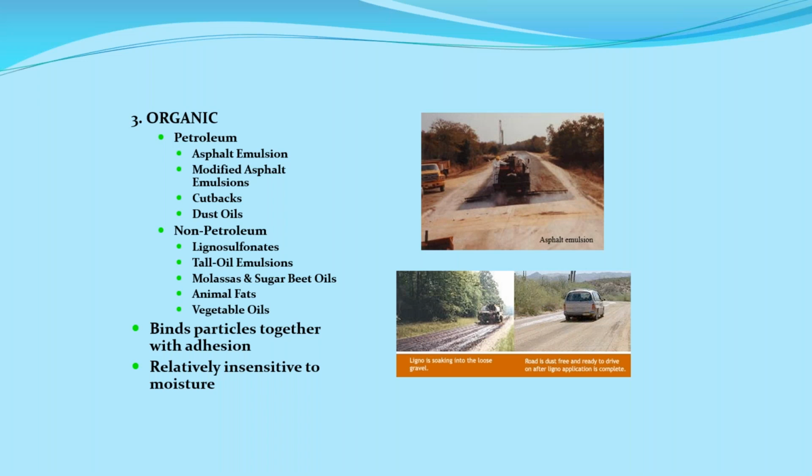But like a petroleum type of product, once it's dried, you're not able to take and regrade it or deal with the surface. And if it starts breaking up like the petroleum type of product, you've got to fix it with the same type of product that you originally did. So on the petroleum types of products, they'll generally take and patch it with hot mix or cold mix. On a cement treated type of roadway, you've got to take and chip it out and remix it together and put in some more cement and more or less patch it. So it creates some problems in your roadways.